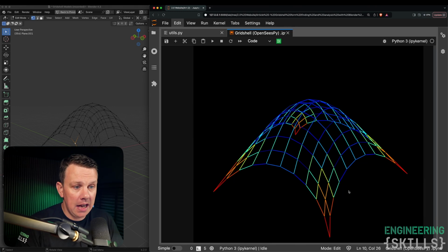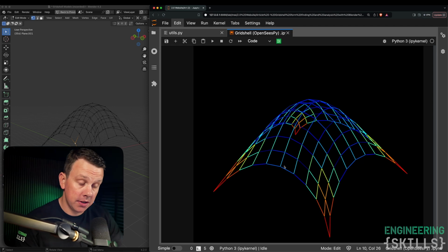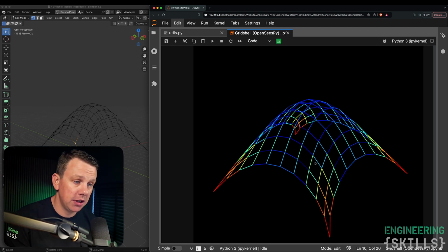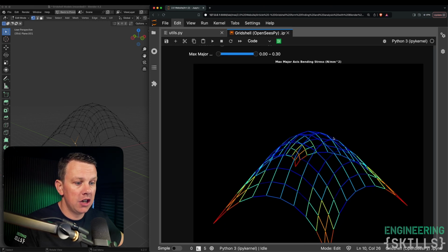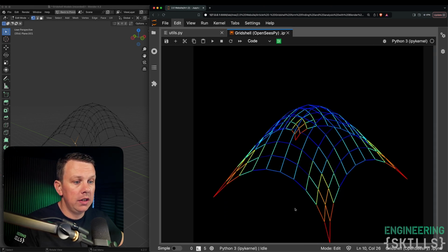And naturally enough, it pretty much mimics what's going on with the axial force distribution, right? We can see, in the broadest of terms, that the larger magnitude stresses are being experienced down adjacent to the supports. And again, we can do the usual tricks where we can change the range of values that we're visualizing. And of course, if we only focus on larger magnitudes of stress, we'll only see stresses down here.